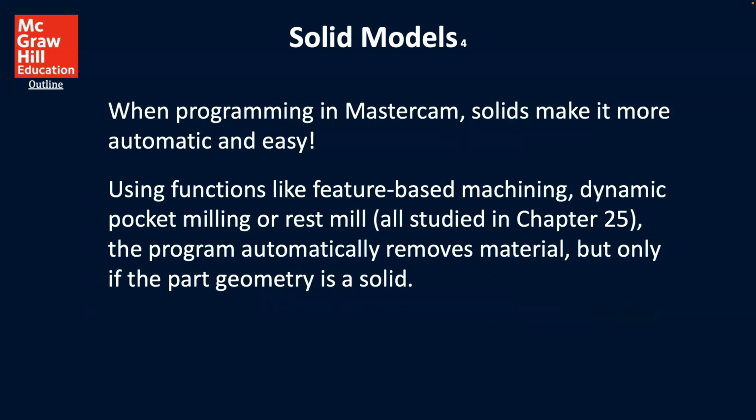When programming in Mastercam, solids make it more automatic and easy. Using functions like feature-based machining, dynamic pocket milling, or rest milling, which are once again studied in a later chapter, the program automatically removes material, but only if the part geometry is a solid.